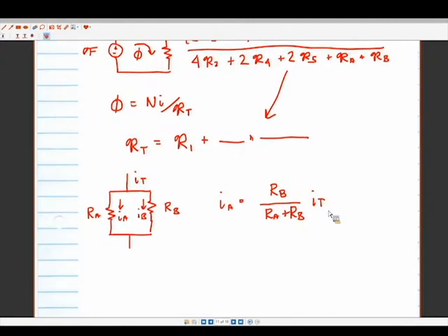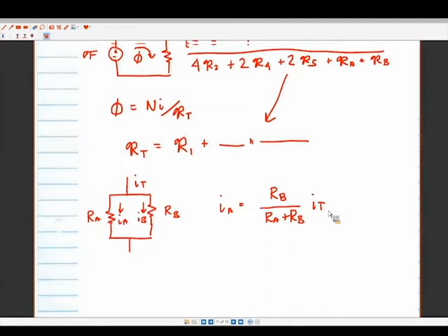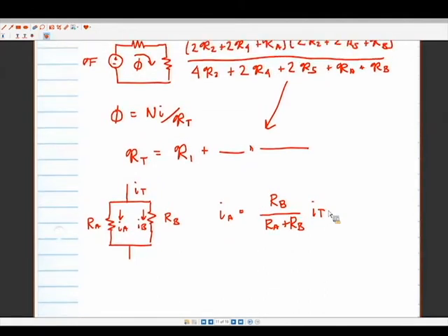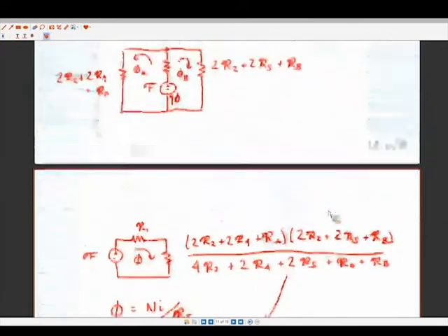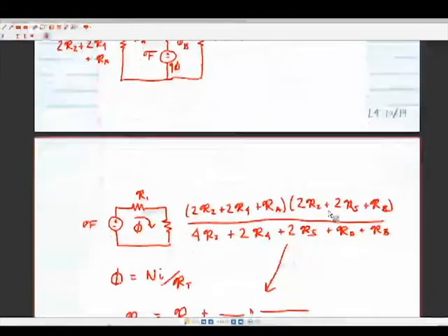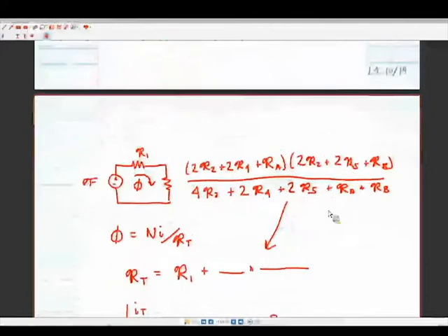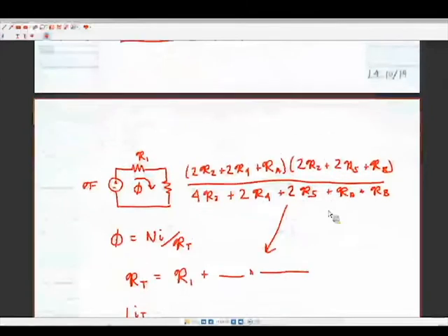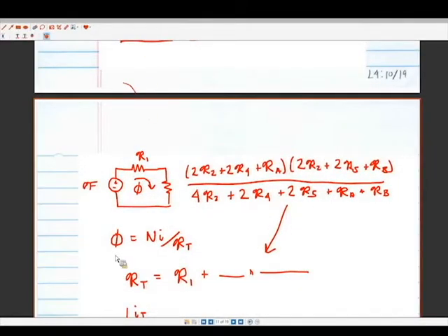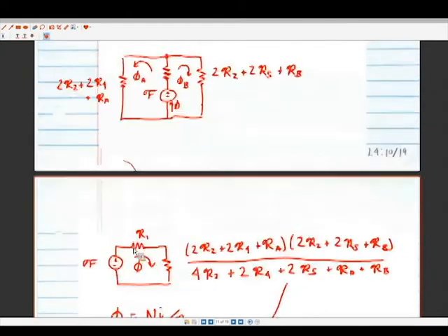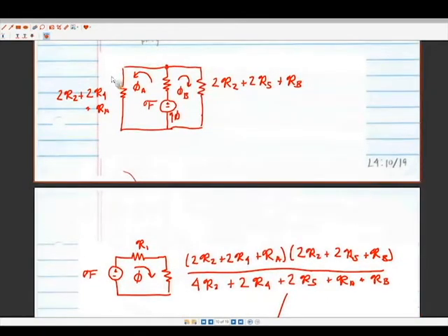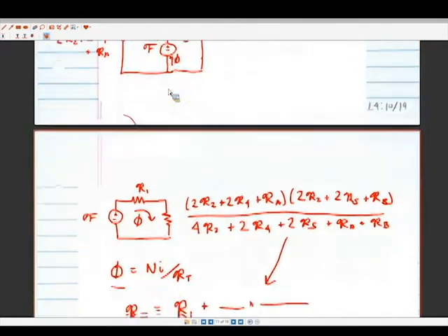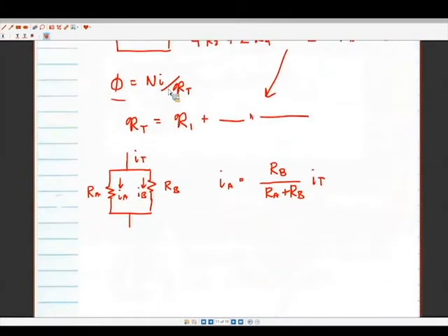Okay, so tying that to our problem at hand. Right, so we have a current divider. We have an expression for total current, which we just, we have a flux divider. Essentially, we have an expression for total flux, which we said is just this regular phi. We know the reluctances of our different links here. And so with that knowledge, we can now understand what is phi A and phi B. So I'll go through phi A. Phi B would be very similarly structured.